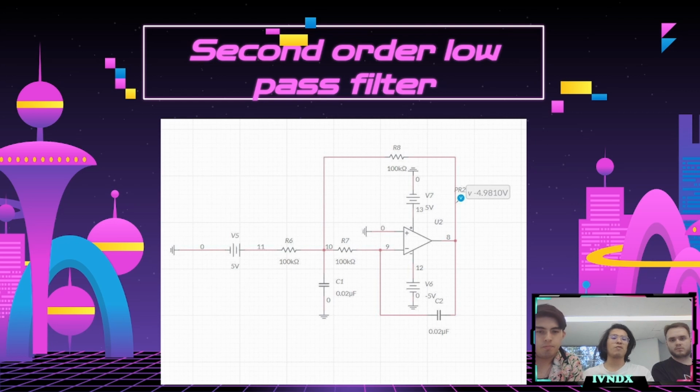that has a maximum of 50 hertz. For this filter, we had to do trial and error with the resistor and capacitor values. Since we are able to assign the same value to each resistor and each capacitor, we end up with a formula where the frequency has to be equal to 1 divided by the product of the resistance and the capacitance.